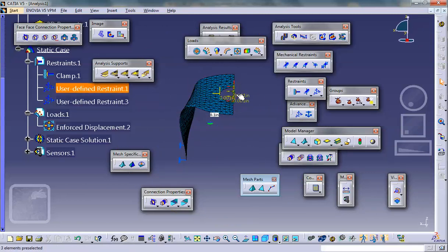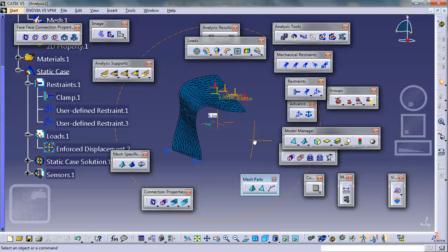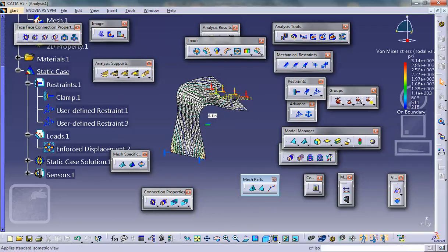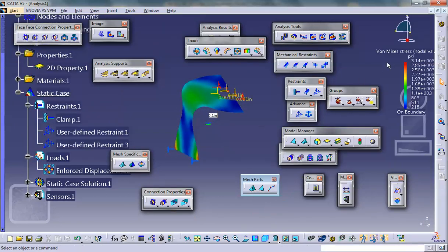And notice that this is all a straight line on the plane of YZ, because YZ is a plane of symmetry. Okay, and then you can look at the von Mises stress and change the rendering. This is how it's going to behave. I showed you the steps. It doesn't mean that the numbers that we get are meaningful, although they're not that bad. But I'm just showing you the steps. The rest of it is your engineering judgment and see whether this von Mises stress, for example, makes sense or not. Let me see, what else do I want to tell you here?